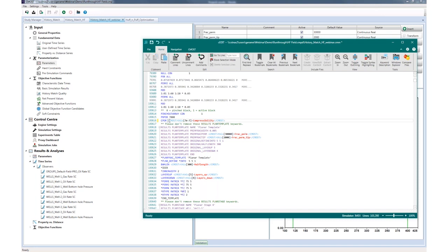And cEdit knows exactly what the CMOST syntax keyword should be to set my rock compressibility as that parameter. And the compressibility is a variable parameter that you will vary inside CMOST, right? Exactly. In this particular case, I would allow CMOST to play around with a range that I've specified for my compressibility, and CMOST would go in and see how that compressibility changes and how it affects my results. Great.